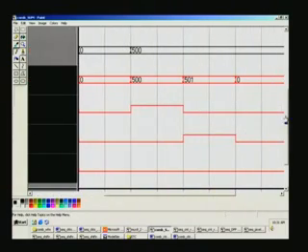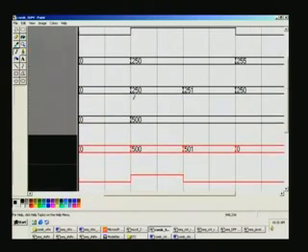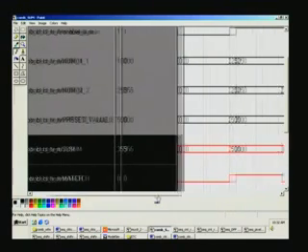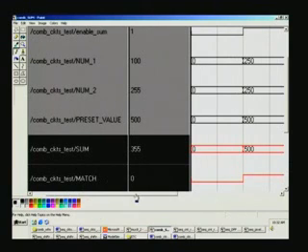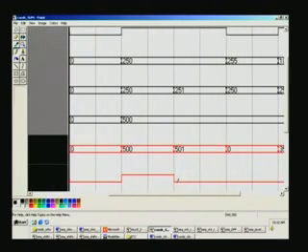So what we had is two numbers here. When you add, it amounts to 500. That is this one. This is the computed value, and now you can compare 500 with the preset value. This is the preset value. So equality is seen here. So the match signal must be on. Is this the match signal? Let us see. Yes, this is the match signal. So you see here, it was 0 all along in either direction, and it goes high only during this equality being fulfilled.